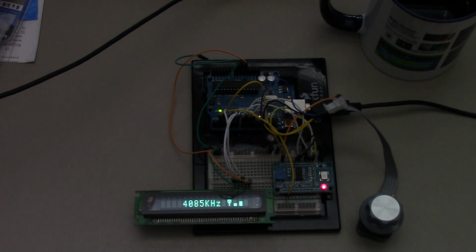The original libraries called for a liquid crystal display. This is going to be housed in a 1U box, so I needed something pretty small, and I happen to have some of these little vacuum fluorescent displays laying around. They're SPI, and I found a library for that and ported the code over to this platform. Along the way I also added some custom characters, changed the way the display was laid out, and came up with some other neat things that I thought would be useful.